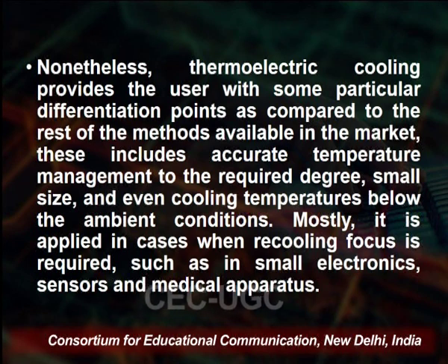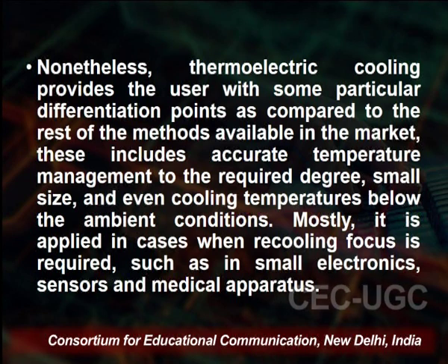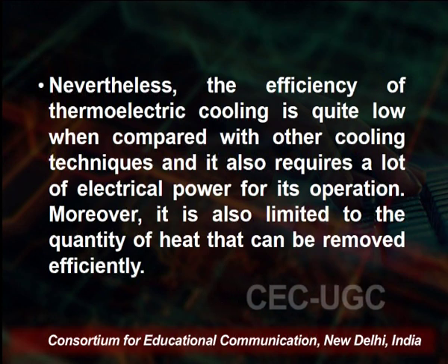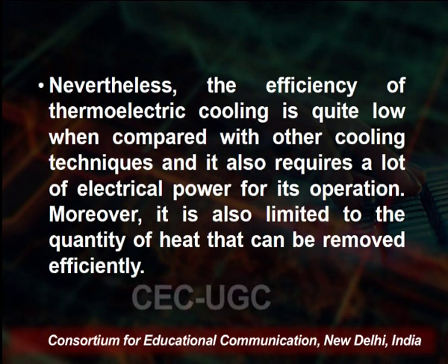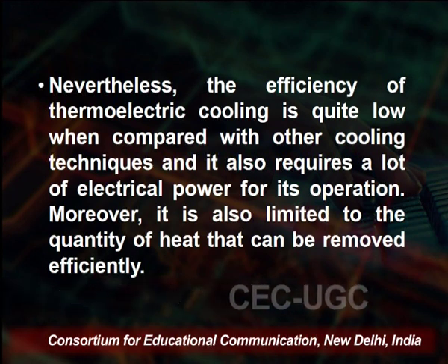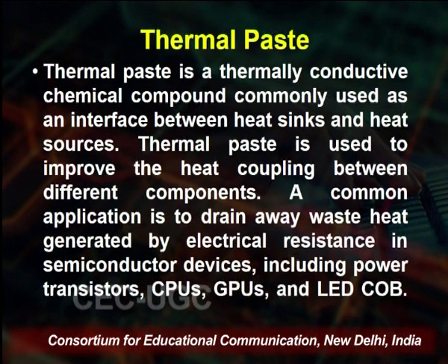Thermoelectric cooling provides the user with some particular differentiation points as compared to other methods available in the market. It is applied in cases when a small cooling force is required, such as a small electronic sensor, and also in medical apparatus. However, the efficiency of thermoelectric cooling is quite low compared with other cooling techniques, and it also requires a lot of electrical power for its operation. The quantity of heat that can be removed efficiently is also limited.